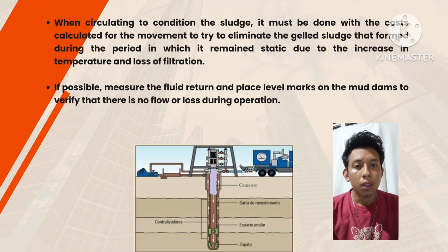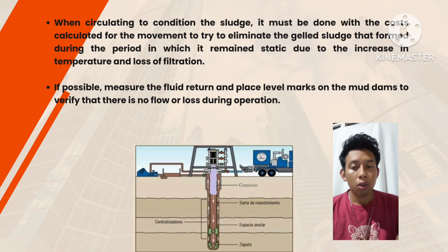If possible, measure the fluid return and place level marks on the mud tanks to verify that there is no flow loss during the operation.